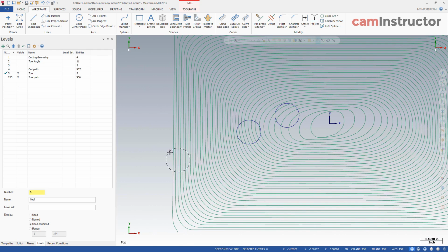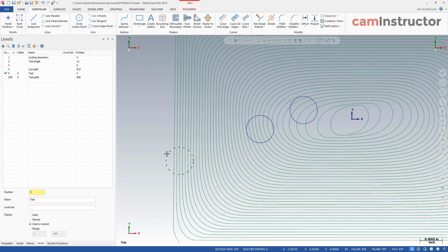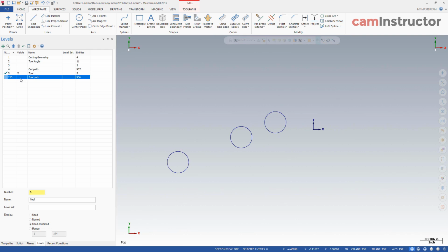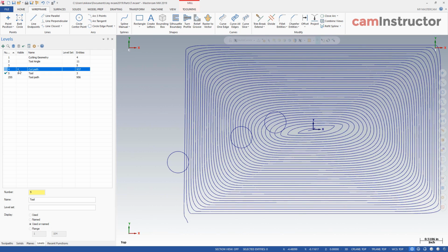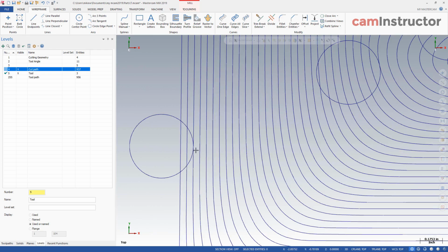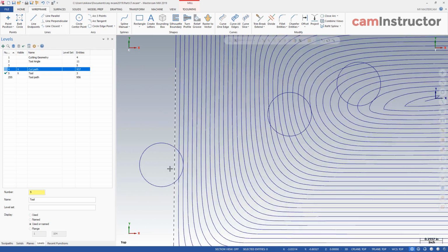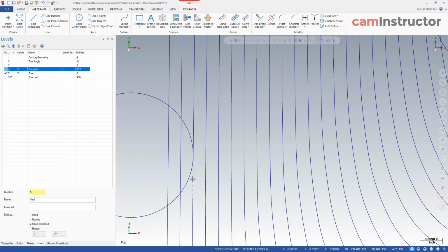Okay, so I've got basically my end mill drawn at different locations along this tool path. And I'm going to turn on the actual cut path now. So this is the profile that the outside of each cutter leaves behind. So basically what happens here was when this cutter went around and it was on this path here, it left this stock behind and it's come back around and now it's following this path. So this is the cut that it's taking right there.